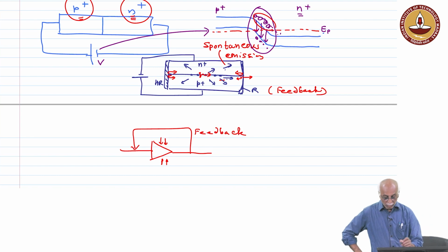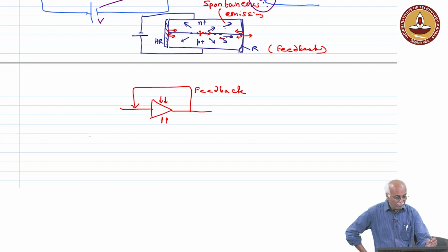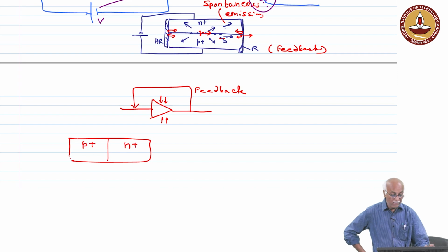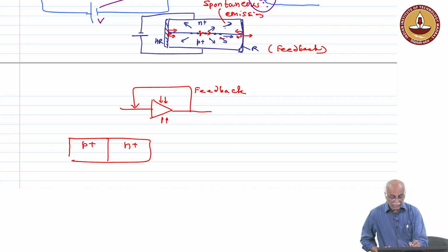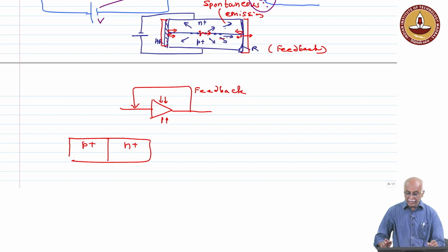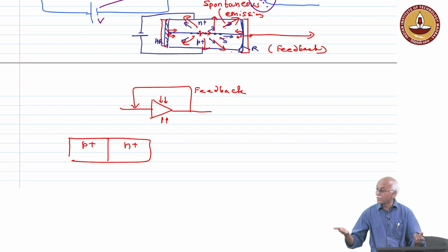Now, as we can see, if it is a homo junction PN semiconductor material and it is edge coated with mirror, as shown here, we see that more or less the output is in this direction. However, there will still be lots of spontaneous emission in other directions, which is nothing but loss.